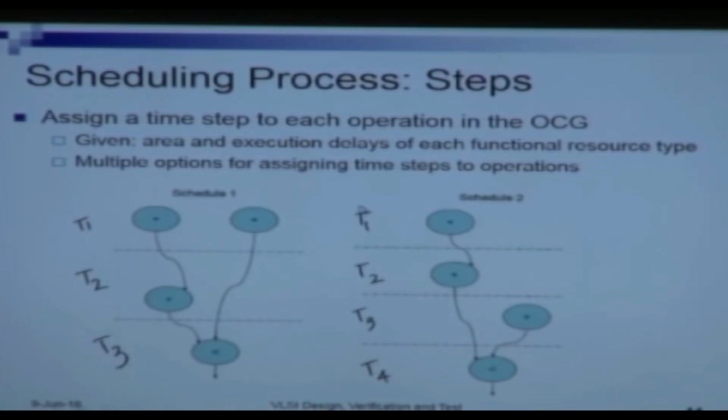means that when I make a hardware circuit out of this schedule, if I make a hardware circuit using schedule 1, I will get a faster circuit as compared to schedule 2. However, the area consumed by schedule 1 is also higher with respect to schedule 2.